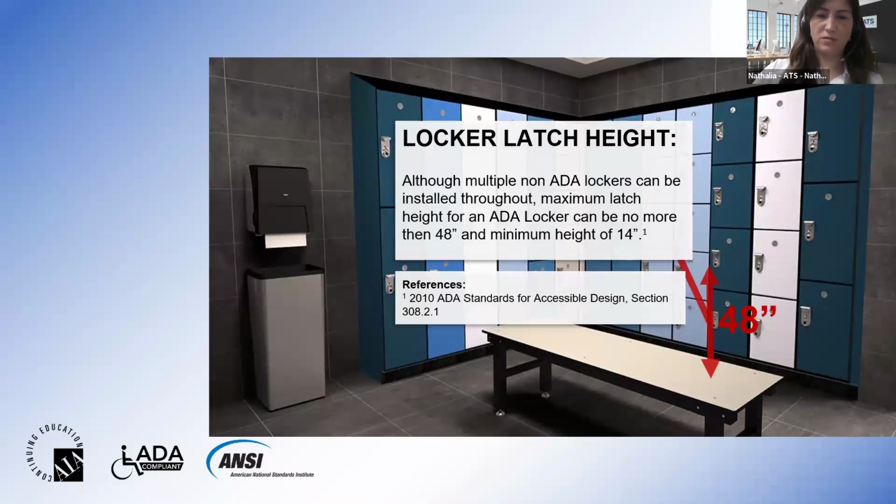I know we have some differences here in Ontario. I guess it's a little bit lower and higher than that. So we have a higher range. Yeah, the millwork hardware would need to be between 33 inches or 860 millimeters to 41 inches or 1050 millimeters.